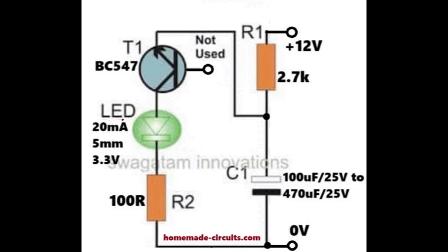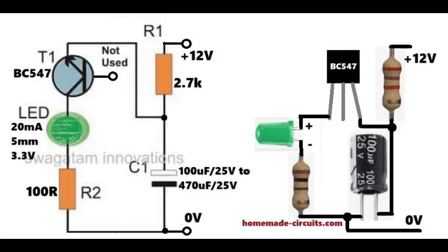The instant it turns on, the capacitor voltage collapses, because the transistor's internal capacitance and charge paths pull its junctions in the opposite direction. This sudden reversal pushes the transistor briefly into a negative resistance region, allowing the LED to turn off again as C1 recharges in reverse. This action repeats continuously, even though the base is floating. The transistor's own junction capacitance, leakage, and regenerative discharge action together form a natural oscillating loop.